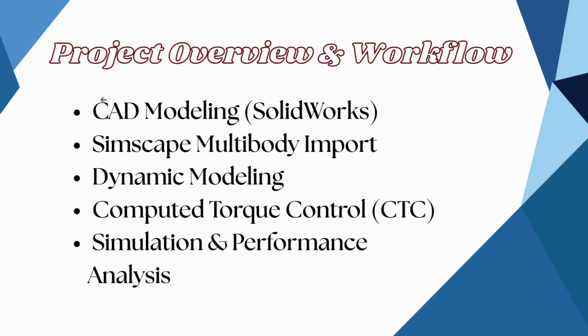The goal of this project is to address these challenges using a model-based control approach. I designed a 4 degree of freedom robotic manipulator, developed a physics-based simulation model, derived its dynamic equation, and implemented computed torque control. The performance of this controller is then compared with conventional PID control to clearly demonstrate the improvement.